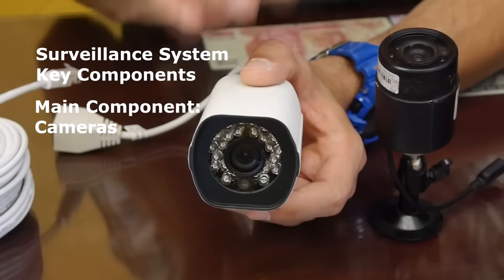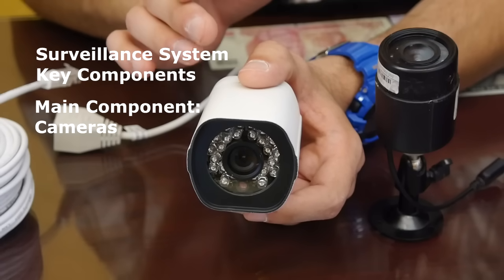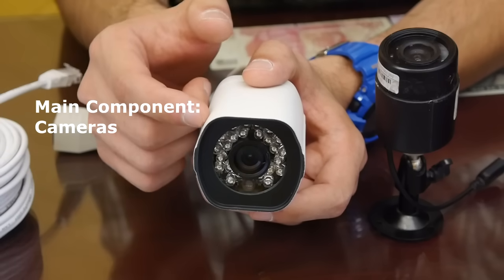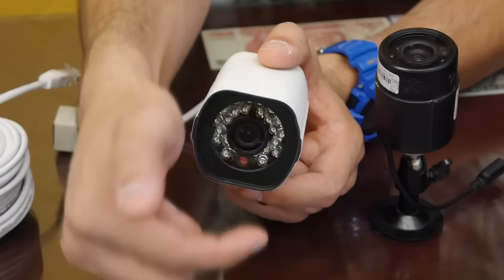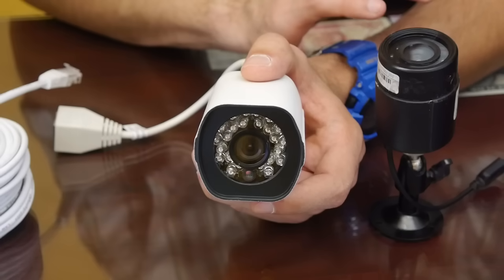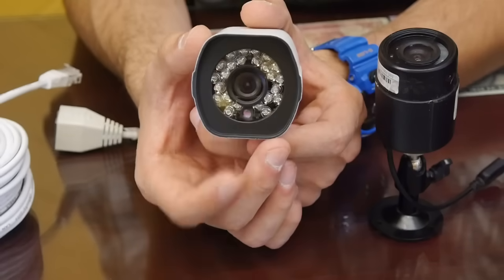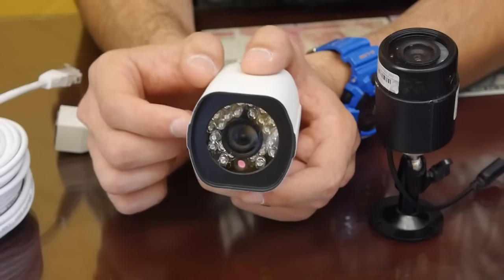The main component of a surveillance system are the cameras, and most cameras today are daytime nighttime cameras. What this means is that they have built-in night vision so they can see what's going on at nighttime. To get their night vision, they use an array of LEDs that blast out infrared light, a wavelength we can't see with our eyes, but cameras have no problem picking up infrared light. These cameras also have built-in light sensors that turn the LEDs off during the day and light up the LEDs as soon as it gets dark.